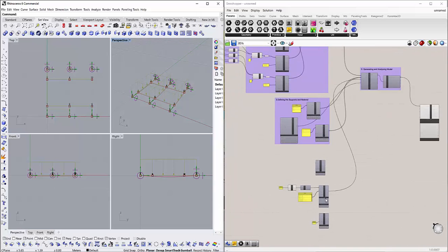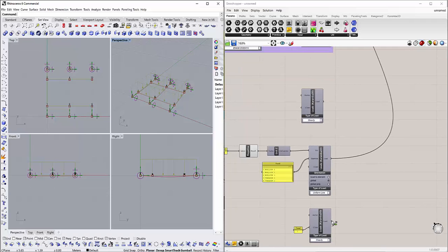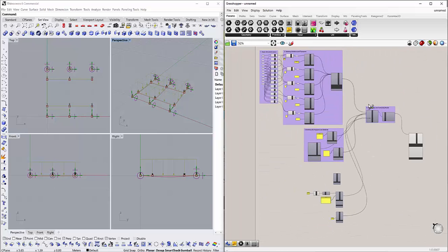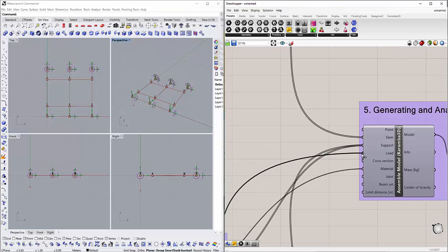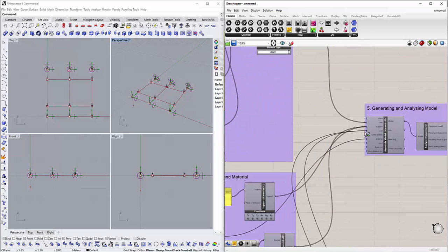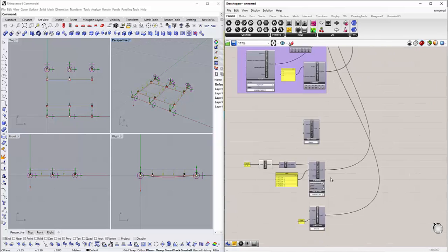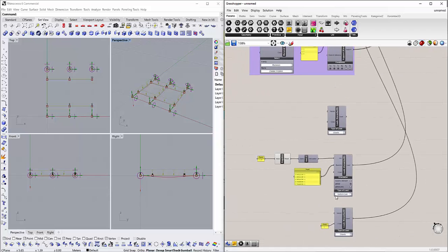So we assigned uniform load. Okay, so the gravity got disconnected, so I'll connect it again. Okay, now this got disconnected. Yeah, so we have now wind load acting on all the mullions and transoms, and gravity acting on the facade. And the third type of load now we have here is that is also a uniform line load.